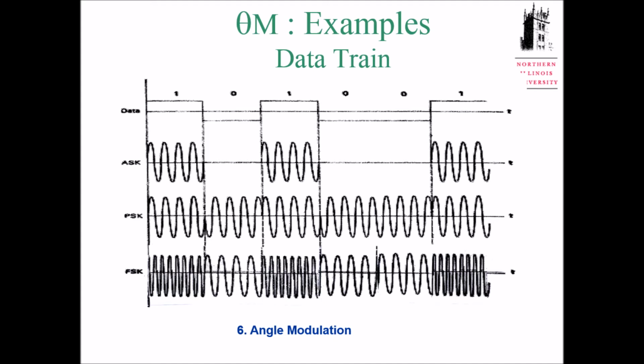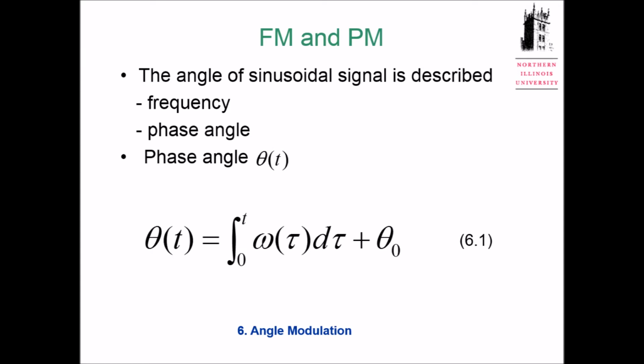For this one, we have a dramatic phase change because your signal drops from 1 to 0 or from 0 to 1. If you find a dramatic change in your phase, that pretty much will be phase modulation. The frequency and phase of the entire signal actually change. Okay, we will talk about more details later.